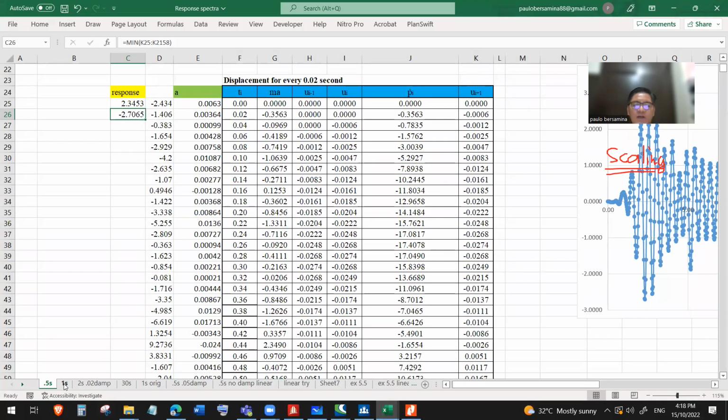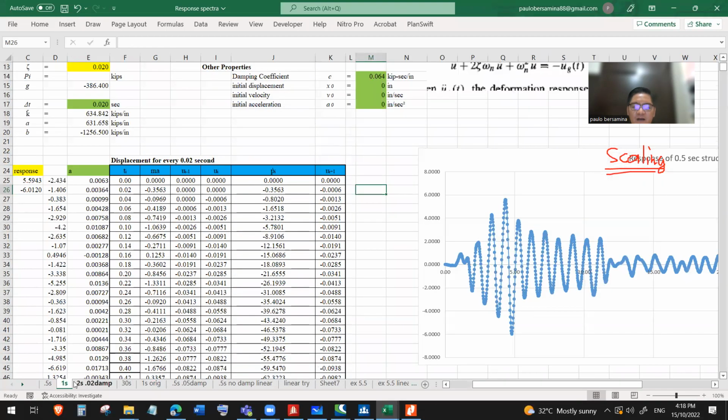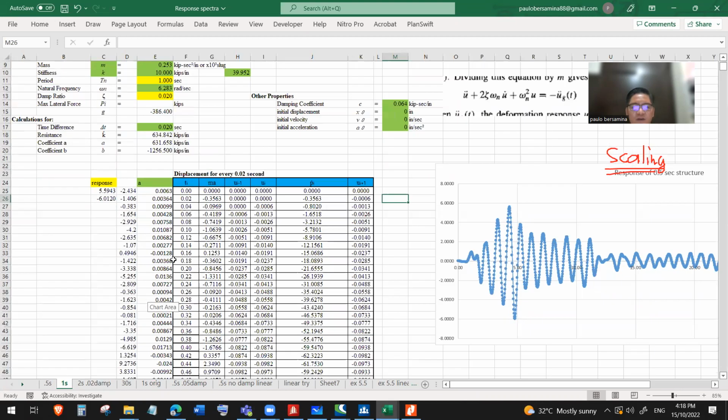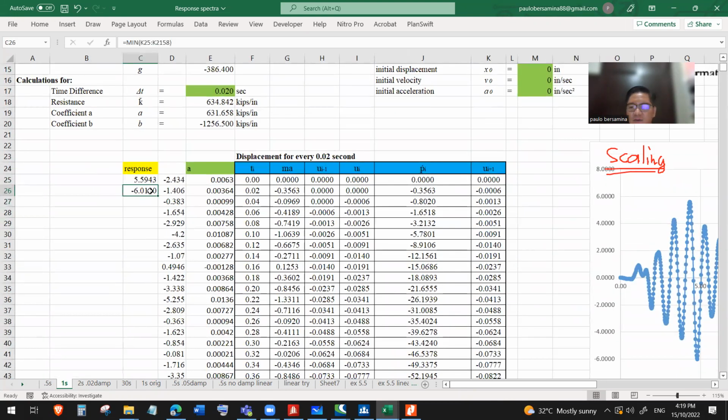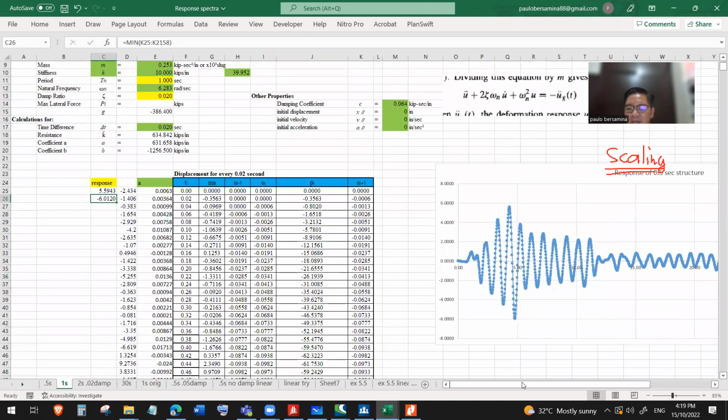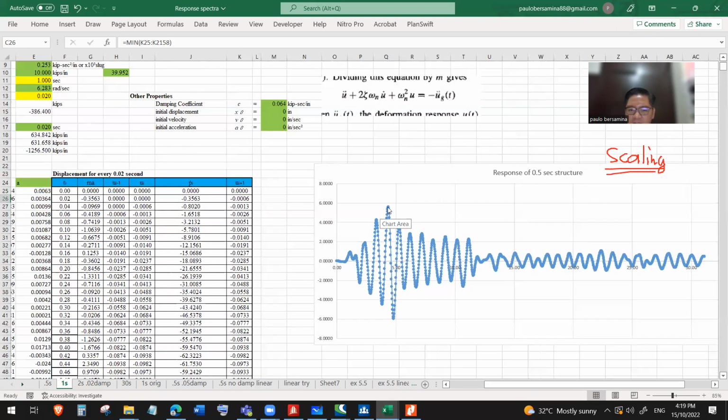5.97, let's see, punta tayo sa 1 second here. Kaya meron akong Excel sheet here for 1 second, or basically 10 story. And using max min function, I got 6 inch. 6 inch here as the maximum displacement. 5.97, 6 inches, roughly the same, no? And when did it happen? Okay. Ito, 4.8 seconds. 4.8.